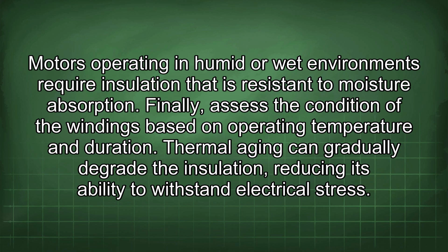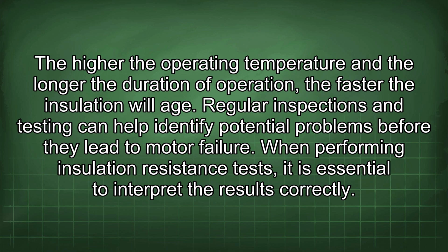Finally, assess the condition of the windings based on operating temperature and duration. Thermal aging can gradually degrade the insulation, reducing its ability to withstand electrical stress. The higher the operating temperature and the longer the duration of operation, the faster the insulation will age. Regular inspections and testing can help identify potential problems before they lead to motor failure.